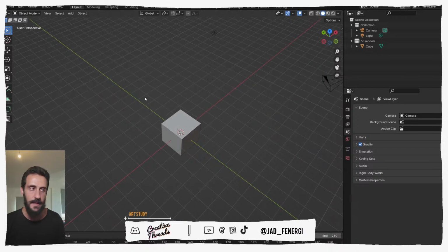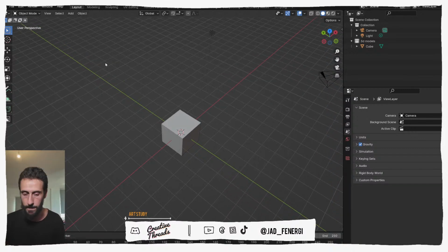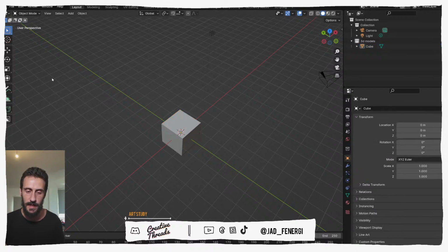Now, of course, in Blender, I usually try to learn the shortcuts and practice them as much as possible, because it makes a huge difference. You become much faster and more efficient. So if you press letter T, you're gonna open the toolbar here, and this toolbar changes according to what you're selecting. So if I'm not selecting anything, I think it's Alt A to deselect everything. I'm still selecting the cube. Okay.